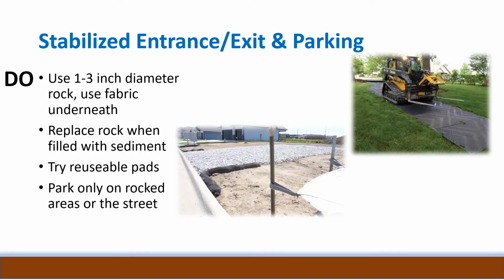Stabilize all construction site entrances or exits. Most communities require this before the foundation is dug. One to 3 inch diameter rock is used with fabric underneath. The fabric will prevent the rock from pushing into the soil. Reusable pads can also be used.